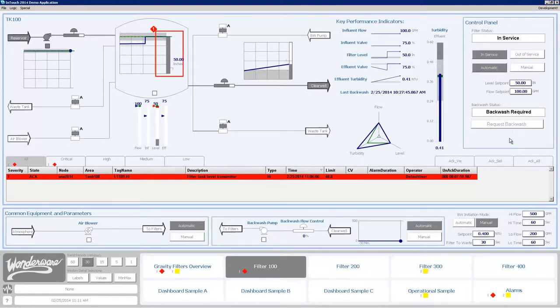So I'm going to start with the first one here, which is an alarm border. Here you can see I've got a tank whose level is currently far too high. It's simulating an overflowing tank in this case. And I'm showing here that there is a Severity 1 alarm. This alarm border is showing that, and it's showing you a way of representing this alarm so that you can quickly distinguish what's happening. You can see that its color is in stark contrast to the rest of the application. And we'll talk about some other alarm borders.